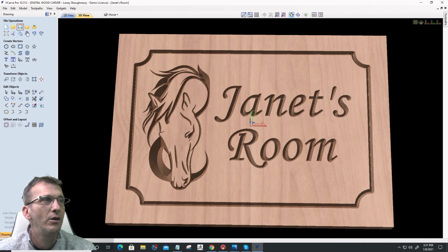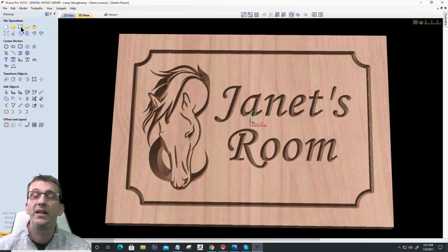So we want to save early, and as we're drawing, we want to come over and save often, update our changes, because there's no auto save in the Vectric software. It may be a feature down the road one day that they put in, but currently right now there is no auto save. It's up to us to save. So save early, save often.